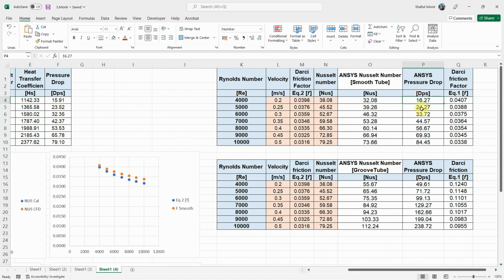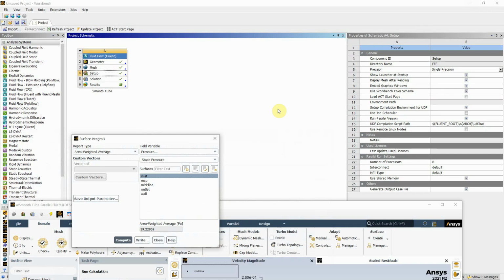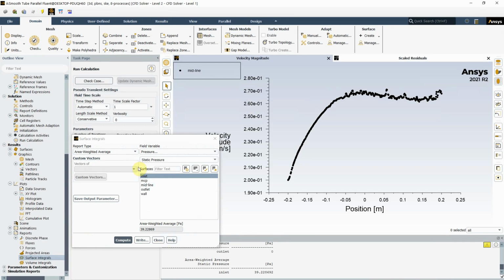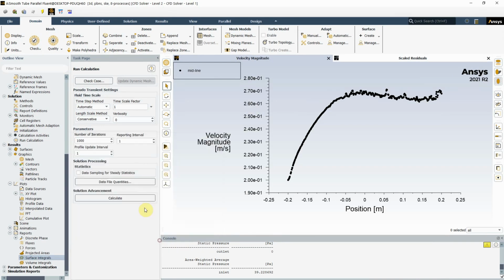in there, you can see that it's quite far away from the Darcy friction factor because it's calculated 0.0981, where the Darcy friction factor should be around about 0.0398. So the turbulence model and the wall function do have a huge influence on the actual results. So refer that back to this. So again here, what you would need to do is look at the wall function in order to see what kind of difference it does.